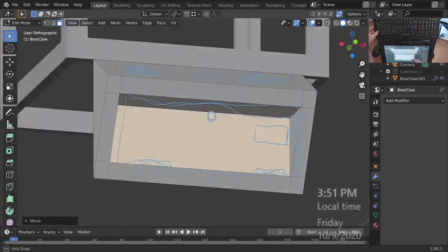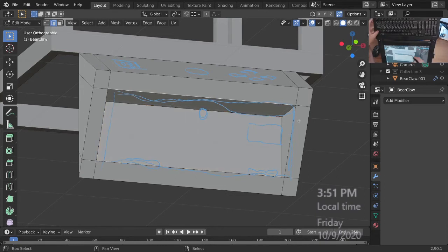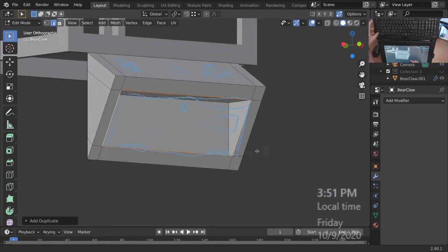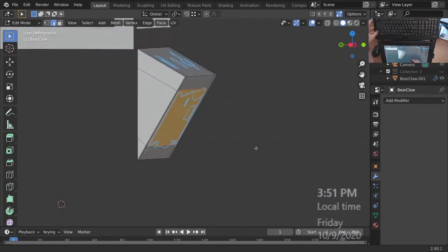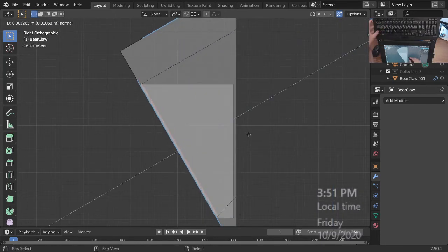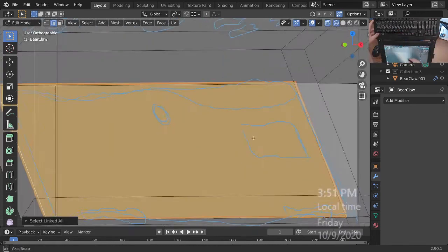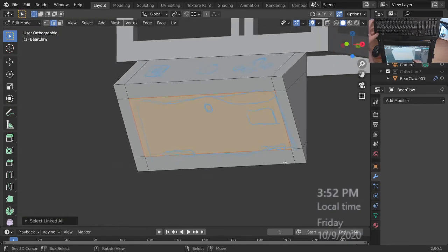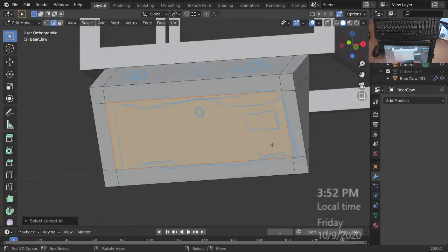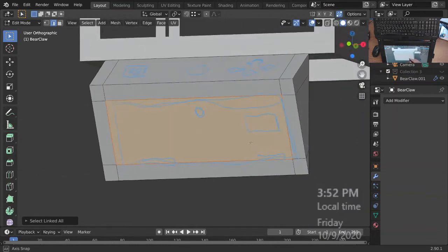There. That works. And then now I take the two edges, the four edges rather, Shift duplicate, fill them in, extrude them out a little bit, Control Link, go back to this view here, and then there is no transform orientation which will give me a nice scale there.